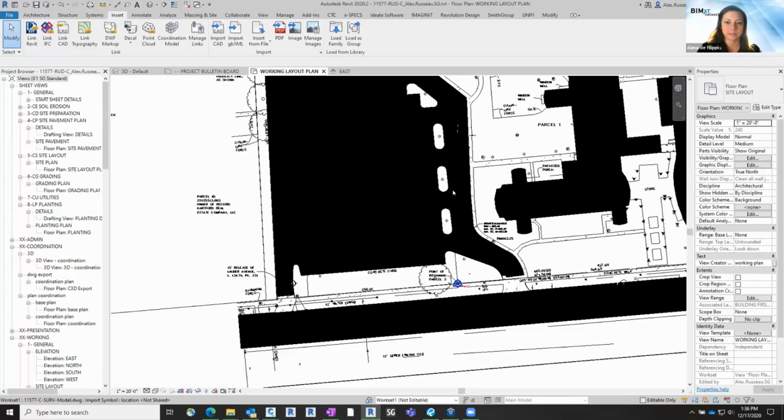In the past I always hated moving the civil engineer's Civil 3D file. I wanted to leave it where it was, and that was where my point was. So I'm really happy that you do that, so I don't have to. But can you talk a little bit about why that's not set up in Civil 3D and why we're doing that in Revit? Is it just because of the translation between the points? Yeah, it's the coordinate translation between a shared coordinate system and the project coordinate system. It does need to make a translation in Revit versus Civil 3D. It's just always real world coordinates. When I link in this file here, it was dumb to start.